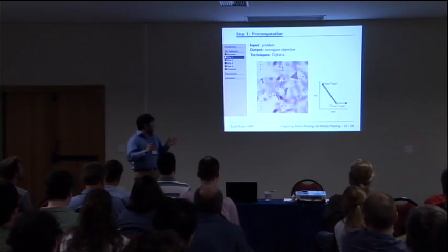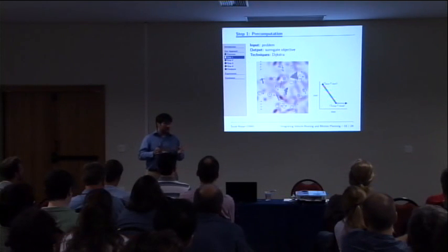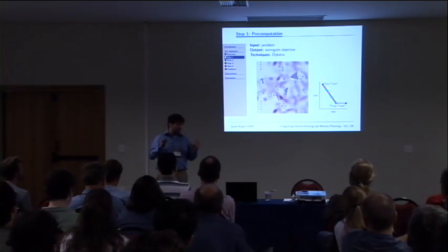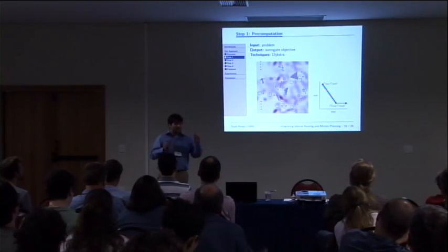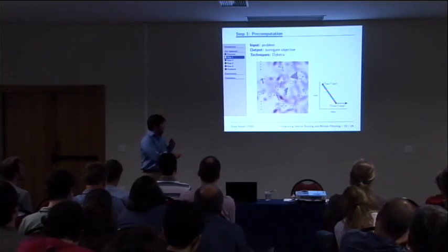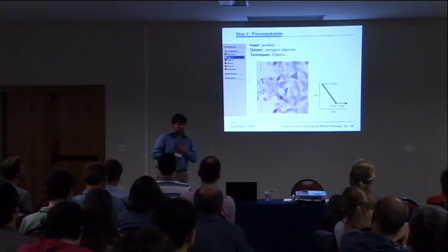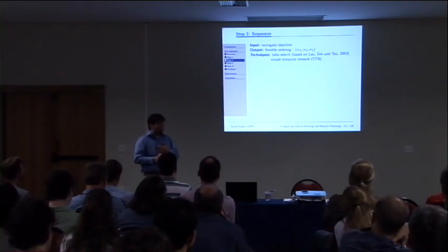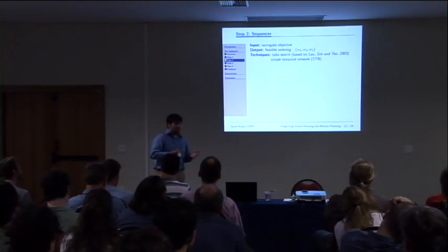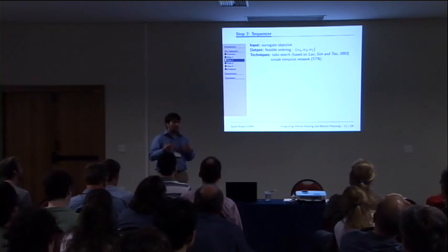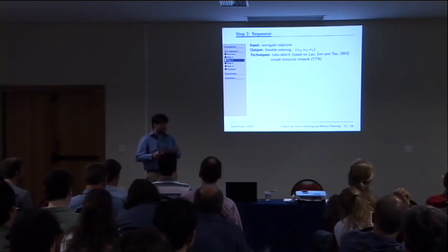We're going to discretize the space and find the shortest path between all the waypoints, as well as the cheapest path between all waypoints. So we get these two endpoints on our line of interpolation. We take this circuit objective, as I'll call it, and pass it on to the sequencer. The sequencer is a local search technique using tabu search, and we keep track of a simple temporal network to maintain temporal feasibility.